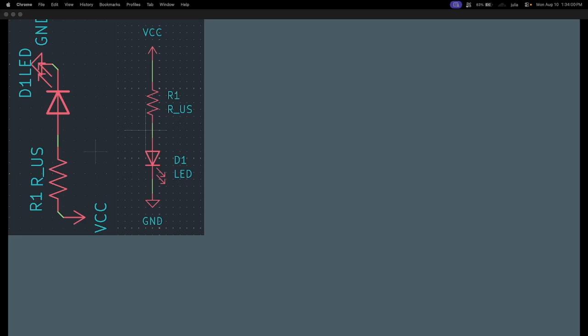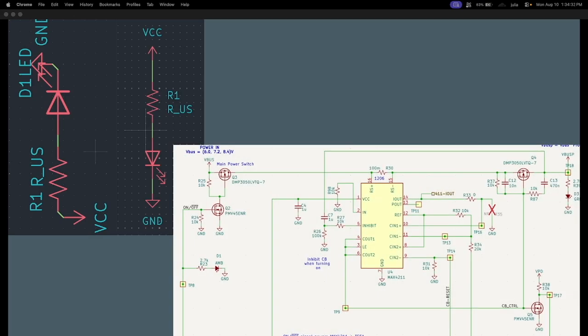So if you were to make both schematics into a PCB, they would be exactly the same because the traces are still connected to the same, not the traces, sorry. The nets are still connected to the same nodes and it's still in the same direction. It's just one is really unorganized for no reason. So they wouldn't be any different, but it's painful to look at. And when you get into more complex PCB design in the future, if you choose to work with more PCBs, you're gonna be seeing schematics like this, and you'll very much want to have good practice and organization when that time comes.